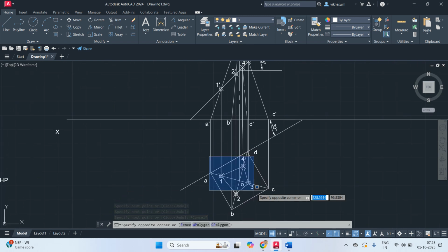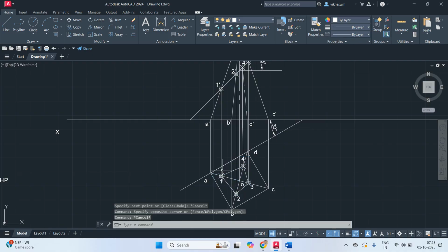Now you can highlight this section separately. Select yellow color, change line thickness a bit. So inside this you have to hatch it. There is an option here, you can see there is an option called hatch. Click on this.